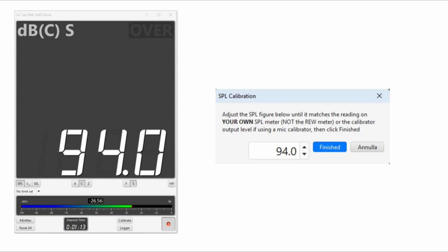It is important to note the reading at the top, which reminds us that we are calibrating channel 1 of the audio interface. Now, activate the generator. Next, set the gain for channel 1, the one where your microphone is connected. Choose a level, visible on the horizontal meter, that is appropriate for your specific application, or required by a standard. If you are performing environmental noise monitoring or measuring musical programs, ensure you leave sufficient headroom for potential peaks.